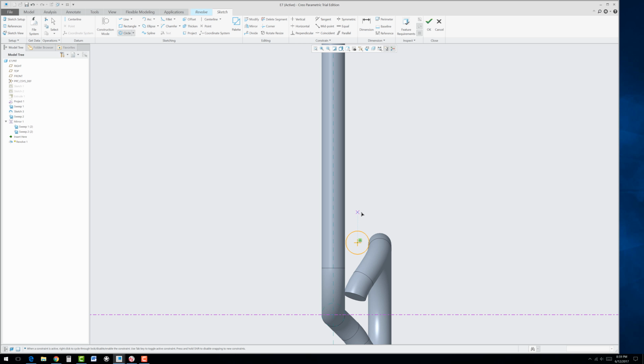First of all, this dimension here needs to be 0.485. We're going to have it dig slightly into the actual geometry of the wire above it, welding it together. If we don't do this, we create disjointed bodies. So we're going to go ahead and do this. Otherwise, you could create it using an assembly too, and then have it wired together. This should be 1.5 exactly.